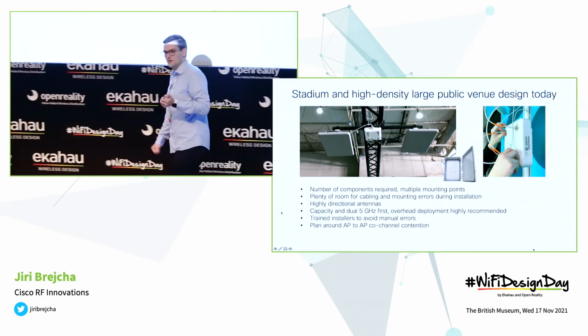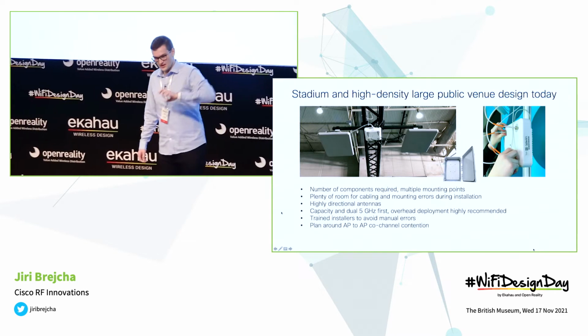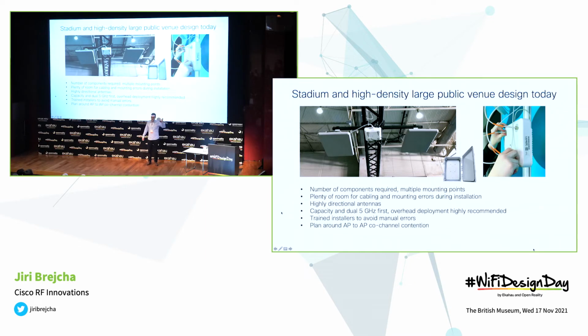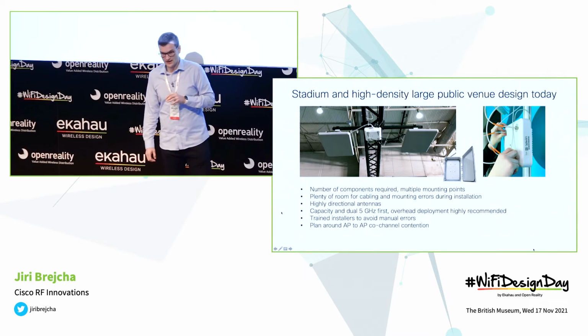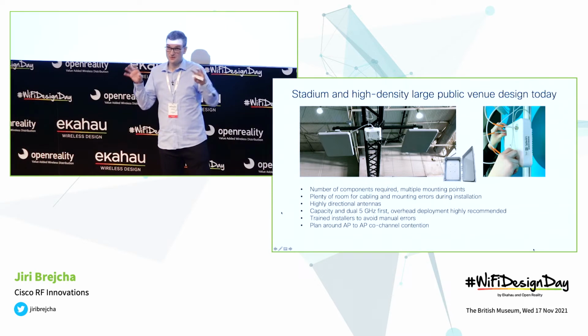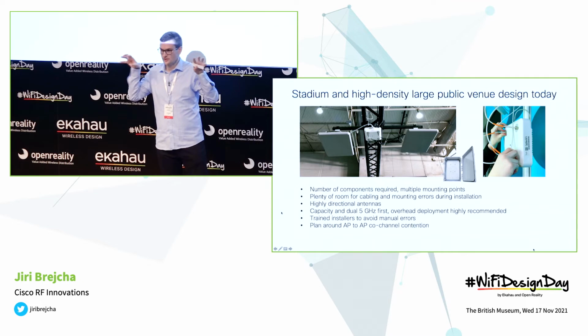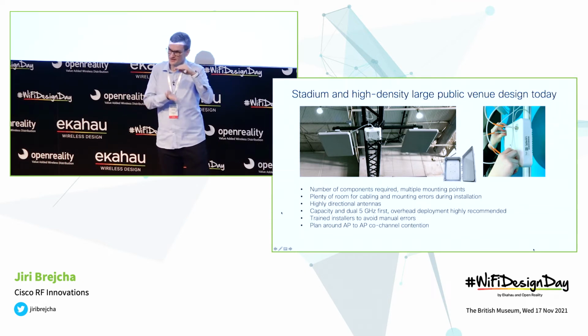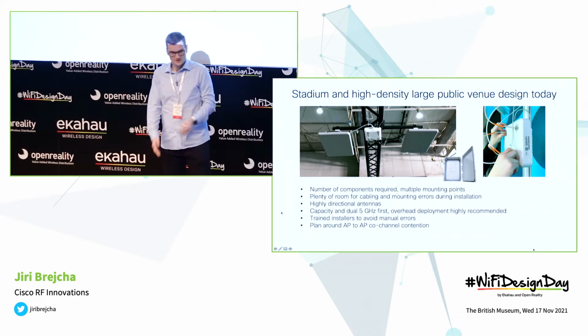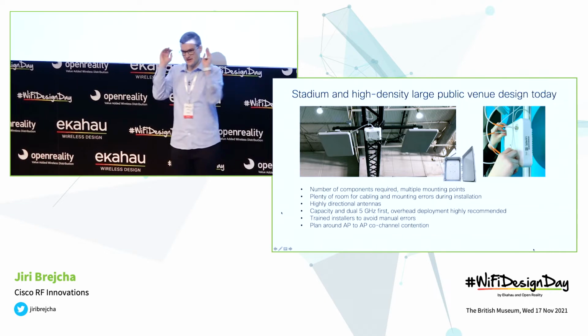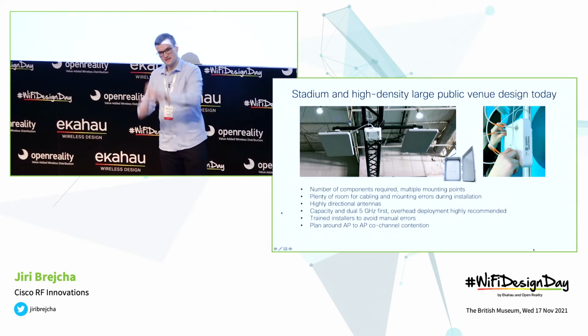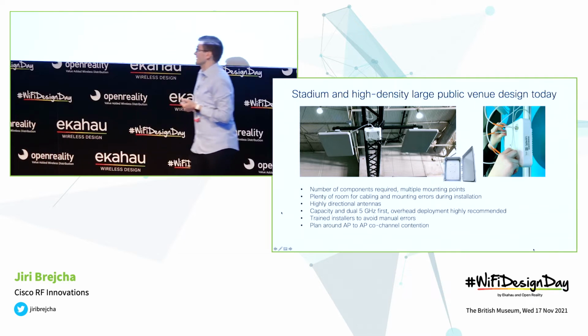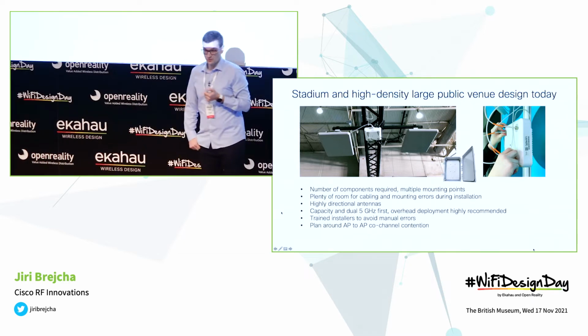The way we would do it traditionally today would be we would use the access points, external antenna access points, and then we have a variety of antennas you could use with those APs, depending on the requirement. We would ideally use dual 5 gigahertz, which gives you 2 nice cells, ideally small cells, as small as possible, so that you only pick up that part of the audience. The other antenna picks up the other clients in the audience,